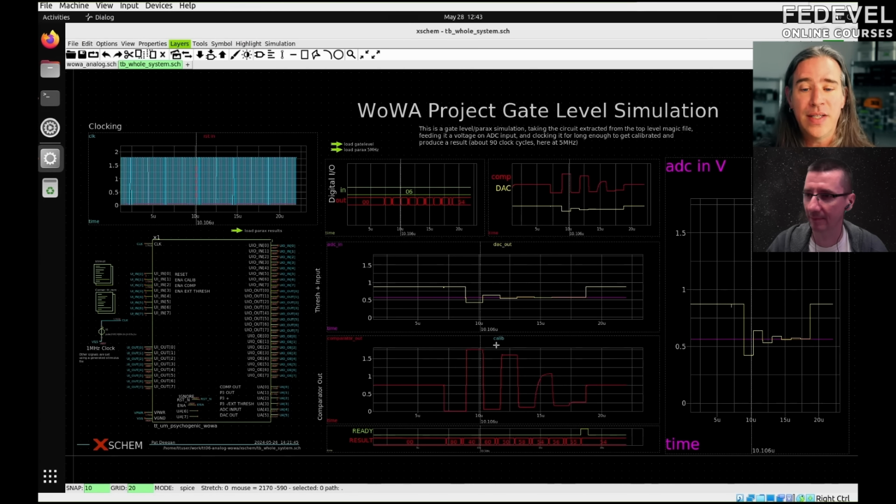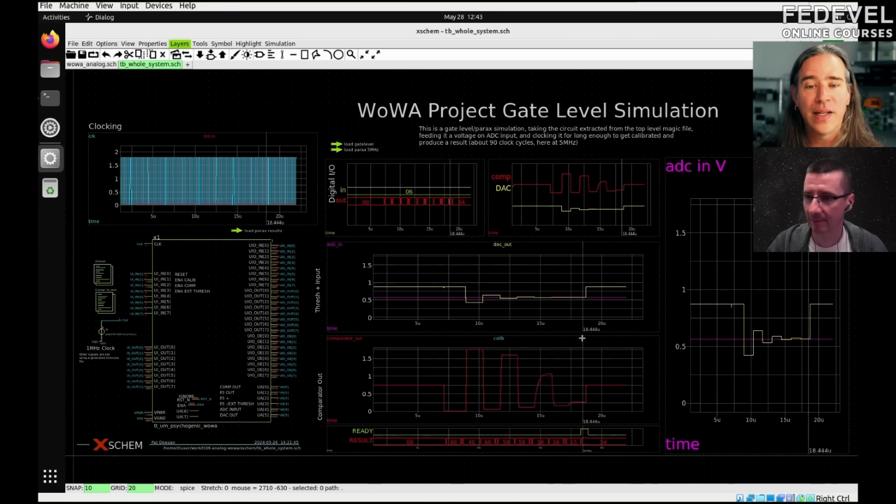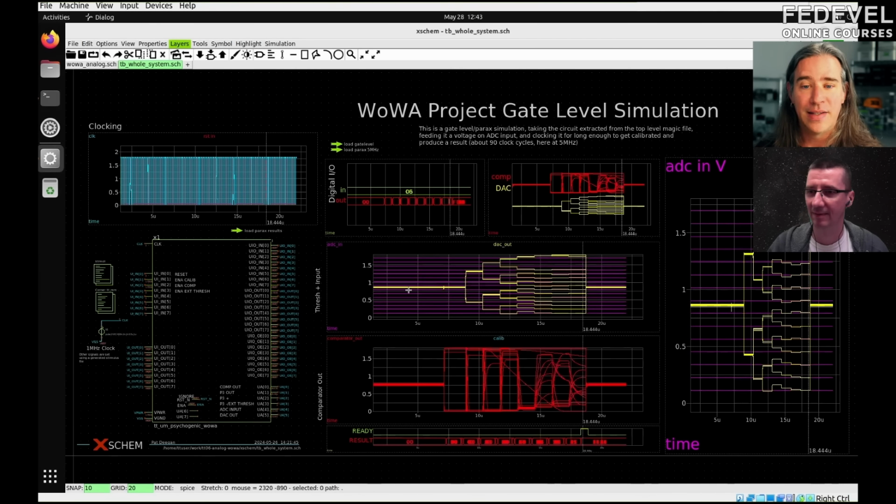And you can see it at the bottom here, the 80 and the 40, and it's whether I'm keeping bits or throwing them away. So at the end of the result here, I go up, down, up, down, up, down, and I kind of target where the voltage is. Each of these runs is doing that for one of these purple lines. And it gets really close. If you look on the right side here, I have a close-up. It gets really close within the number of bits that I had access to, because it's only 8 bits.